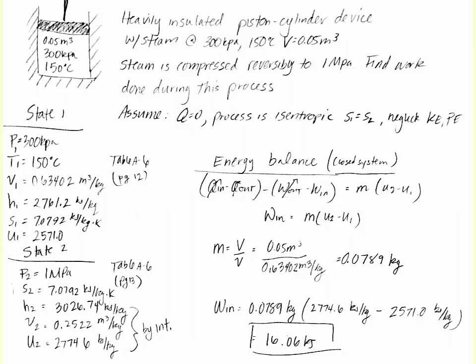But for an open system, we now have energy coming into the system due to the mass that's flowing in, and the flow work is equal to PV. So there's mass coming in with some pressure and specific volume that's equal to the flow work. This term came up so many times that they decided to develop something called enthalpy, which is a combination property.